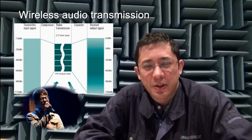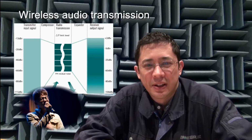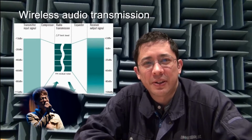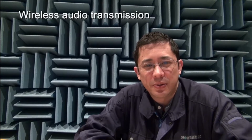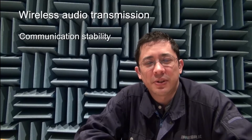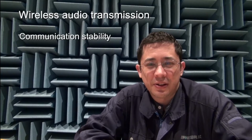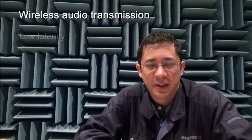To optimize audio quality, Circuit Design implemented a process called companding. This produces good dynamic range even in the bandwidth limits. At the receiver, the module can perform decompanding to restore the dynamic range. For stable communication, these modules use analog FM modulation, which is immune to fading and dropouts. This means it does not suffer dropouts, as would likely happen in digital communication.